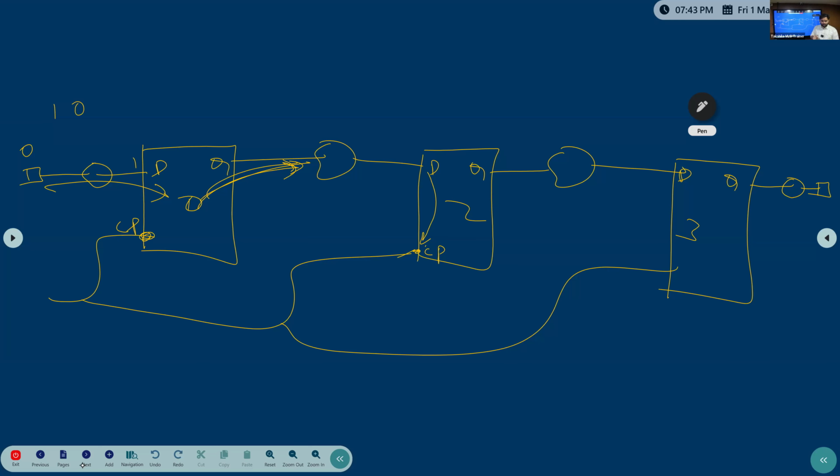These are the interview bits, whatever MCQ bits, they will ask these things only. What is the setup time equation? What are the gates' on time or off time? What is the hold time? When can I say my timing is met, yes or no? What are the timing arcs you can observe, from D to CP, CP to Q? These things only, nothing else will be there. They want to check whether the candidate understands the internal concept. If you understand the internal concept, then this calculation is as easy as drinking water. That internal concept is what matters.